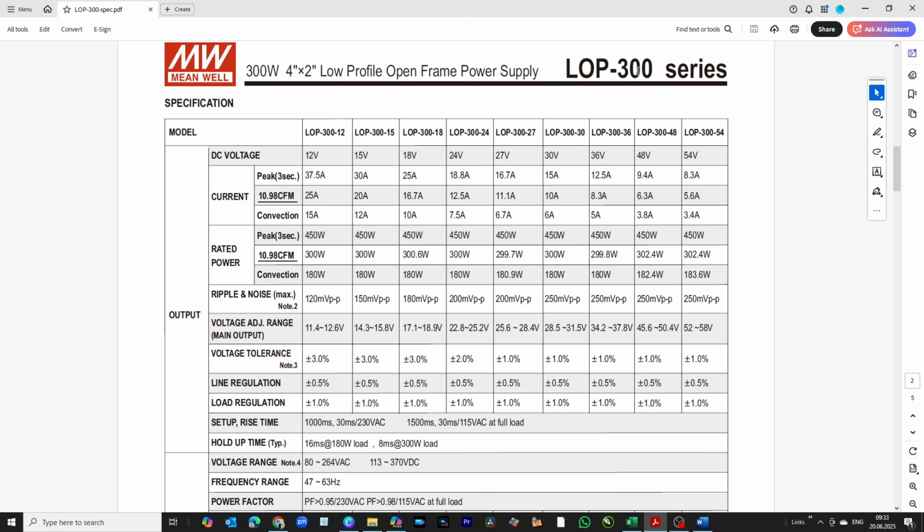So we are using a 300 watt power supply, but at peaks it can do 450, and it really can. And there are no thermal problems with that. It's running almost cold due to the audio signal crest factor of 8, because this is built to really drive LED systems, with continuous consumption, and it can do peaks of 450.